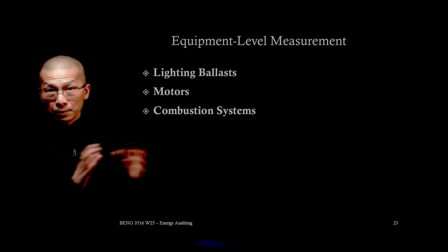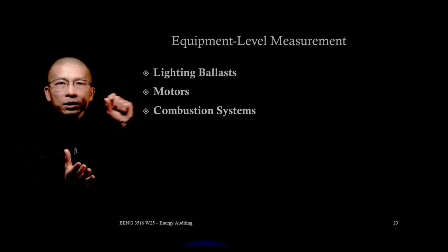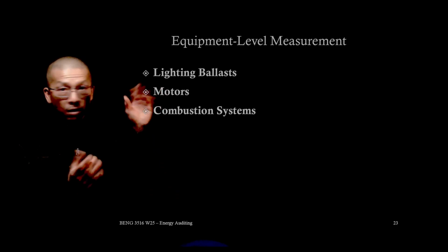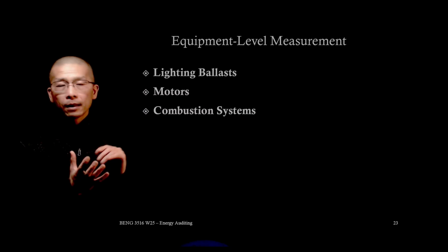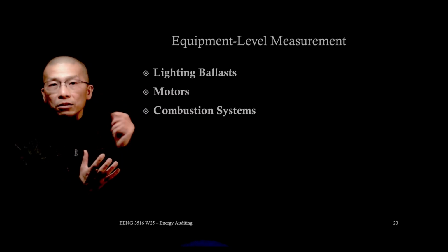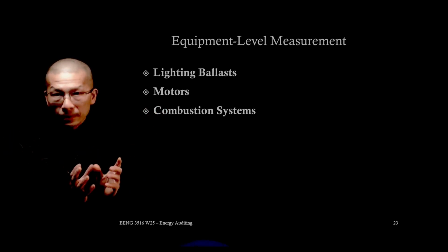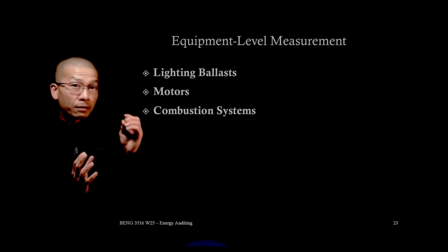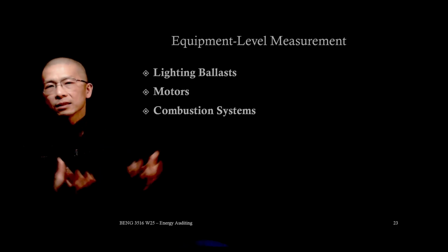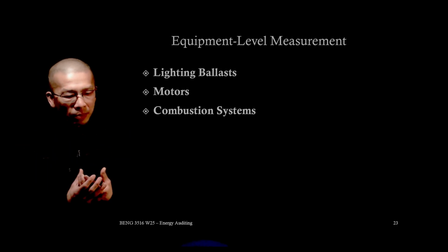If not, it becomes a waste. And also what is in the flue gas, the exhaust composition. By looking at the composition, we can determine the combustion efficiency, or sometimes detect incomplete combustion.